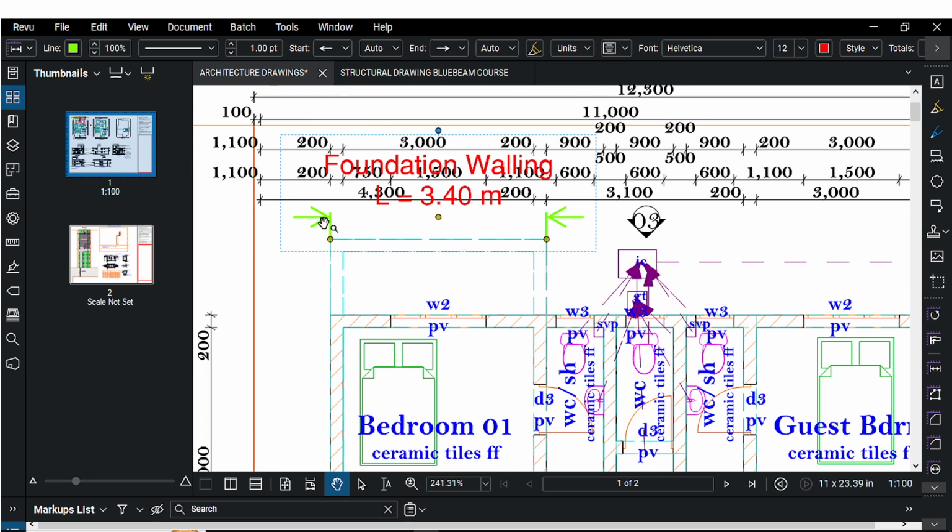Now it is important that I stress this. Yes, we have added this particular measurement as a length, but under the unit you can produce an area by adding a depth. So this depth is actually typed, it is not measured, you type it. For example, if I say the depth, which of course is similar to the height, is 2, the length that is going to be produced can as well produce the area, which is the product of the length here. For example, this is 3.4, and then the depth, which is 2. Remember, the depth here is like the height. If you have the slope here, it will also be used to produce the final area.